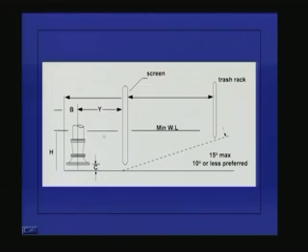and that is the reason why we need to have this sloping floor, because the depth here could be very low, and if I take the floor at this level, then we would not have a proper entry into the pump. There are conditions on how much spacing should be there between the bell mouth entry to the pump and the floor, and what is the minimum water level required for the submergence of this bell mouth when we get better efficiency, what should be the distance between the pump center line and the trash rack and the screens, and so on and so forth.